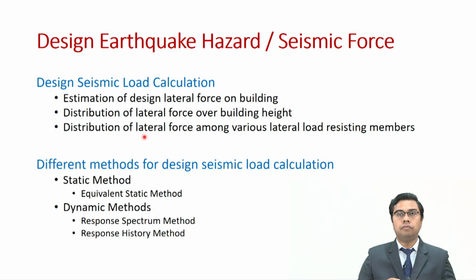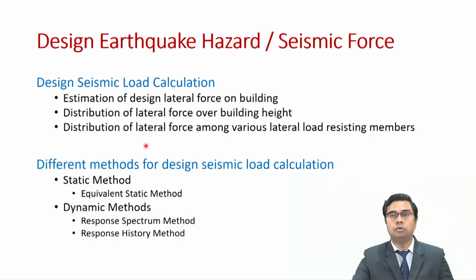For this, we will look into various methods typically belonging to two different classes, that is static method and dynamic method. In this course, we will be looking into equivalent static method as part of our static method, and within the dynamic methods we will look into two different methods, that are response spectrum method and response history method. In today's class, we will look into equivalent static method.